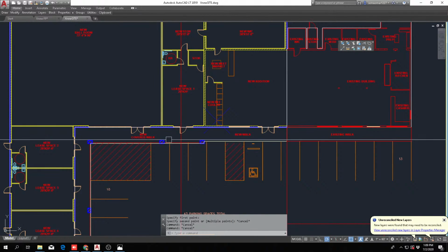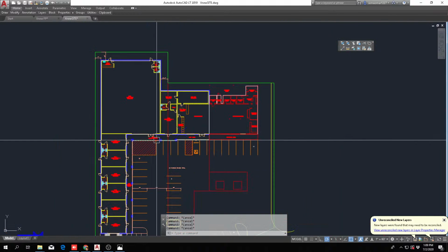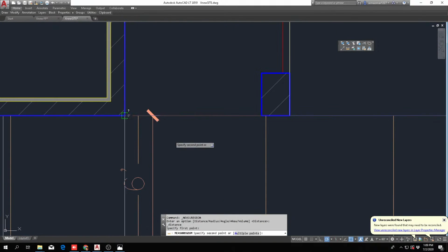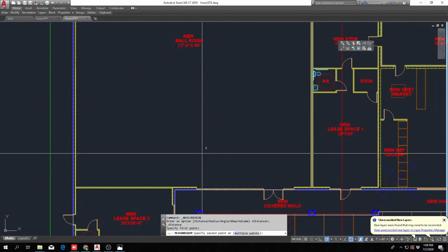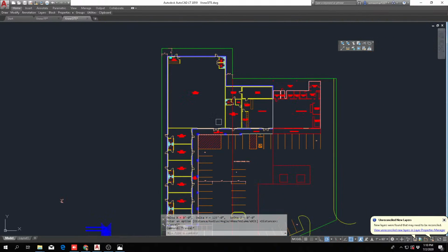Or it can also be a 0.5, because you can cut a 16-inch block in half. So make sure whenever you're doing blocks, it always ends up being in block dimensions.